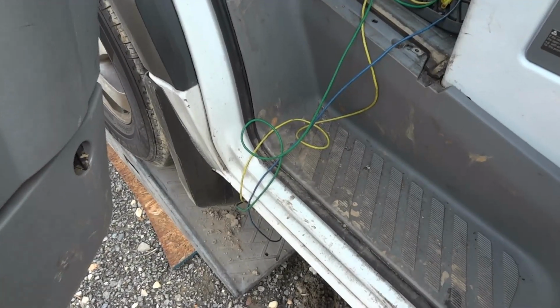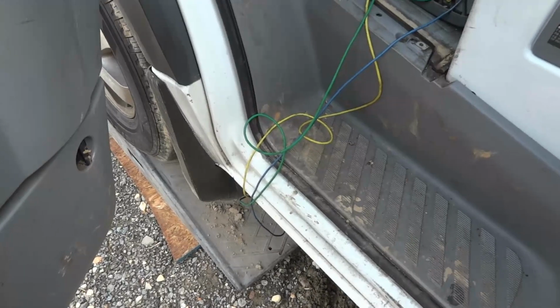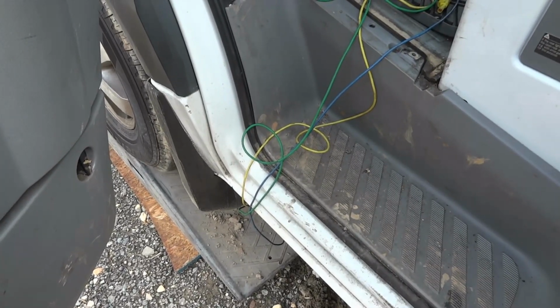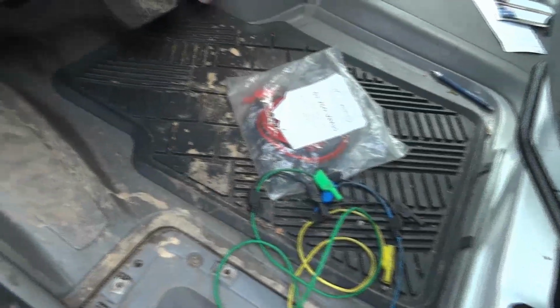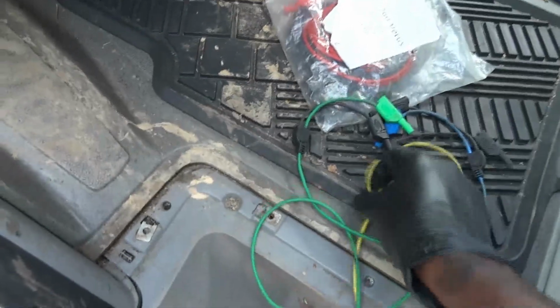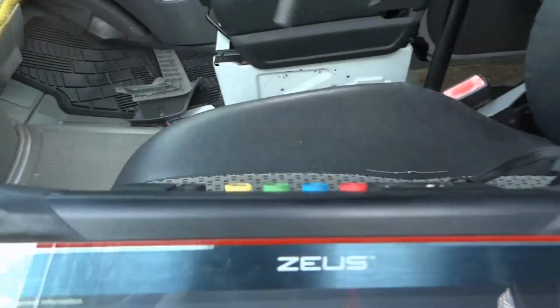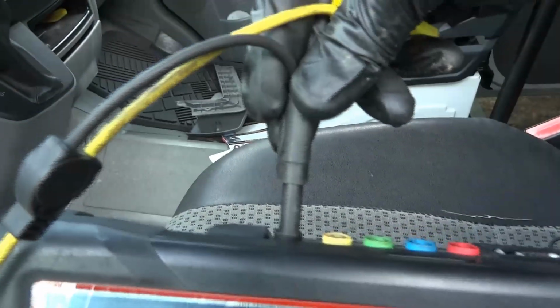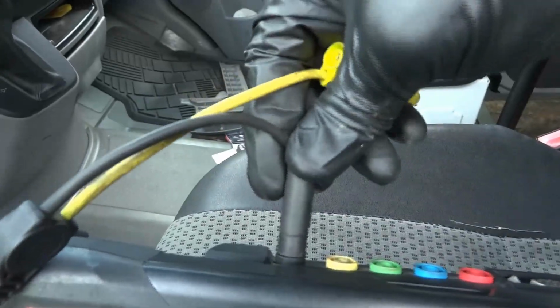So now let's go inside the vehicle and look at what we're gonna find on the lab scope screen. So we got our test leads coming from under the vehicle right there. And these test leads are coming from the crankshaft sensor electrical connector, okay? So now we're gonna connect these to the lab scope. So the first one is gonna go over here. Now we just need to connect the first ground, the one on the first channel.